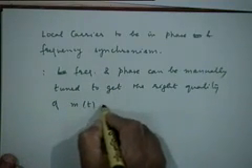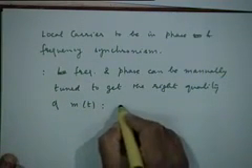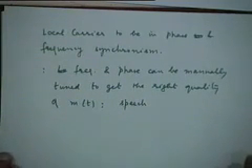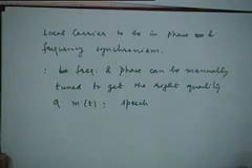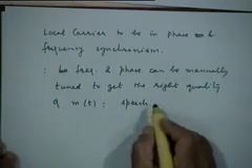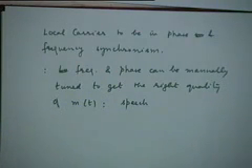And this is particularly doable when m(t) happens to be a signal which you can hear, right? Like speech or music, particularly speech. One doesn't use SSB for music ever, right? So typically for speech, till you get your quality back and the intelligibility is good, you can keep on tuning it. Manually do it over here.